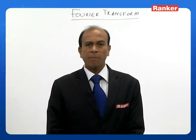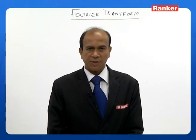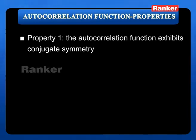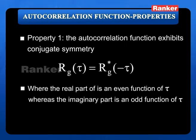Now, let us look at the properties of the autocorrelation function of energy signals. The first property is as follows. Property 1 says the autocorrelation function exhibits conjugate symmetry, that is Rg of tau is equal to its complex conjugate Rg star of minus tau. Here the real part is an even function of tau, whereas the imaginary part is an odd function of tau. So, property 1 says that the autocorrelation function exhibits conjugate symmetry, that is Rg of tau is equal to Rg star of minus tau.